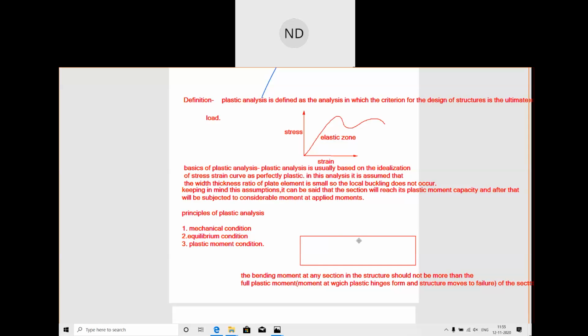You understood what a plastic moment is, and why we do plastic analysis. We need to find the plastic moments, because the plastic moment converts the normal stress into yield stress, and because of this the beam member cannot take up any additional moment, but may maintain this moment for some amount of rotation. It may act like a plastic hinge, which means there is no capacity to resist these moments.